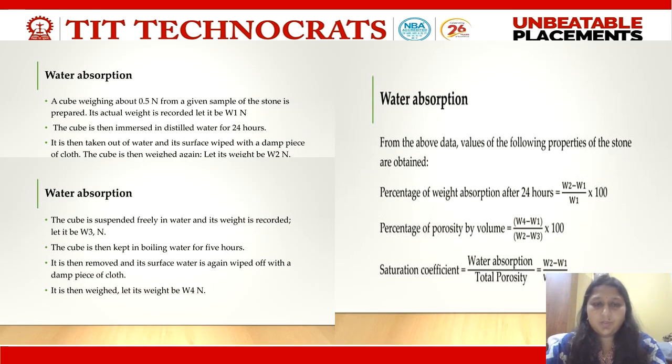Next is my water absorption test. It is a very simple one. Initially, I'll take a stone sample whose weight would be taken as W1. Then the cube is immersed in water for 24 hours. After removal and cleaning its surface, I'll take its weight as W2. So the percentage of water absorption after 24 hours would be (W2 minus W1) by W1 into 100.